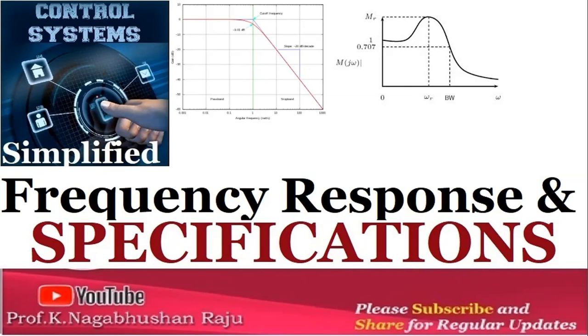Now we need to understand what is frequency response. As we know, the response is of two types: one is the transient response and the second is the steady state response. The transient response can be found using the Fourier integrals. But the steady state response of the system for an input sinusoidal signal is known as the frequency response. We'll focus mainly on the steady state response here.